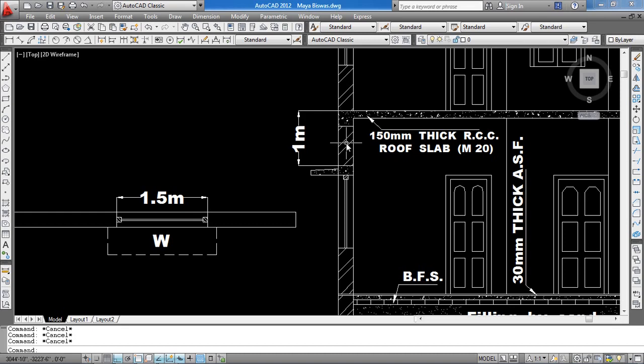Okay, now calculate the length, breadth and height of the wall and also the beam, and cross with the unit weight, for brick 19.2 and for concrete 25. Okay, and the total load will act on the lintel.